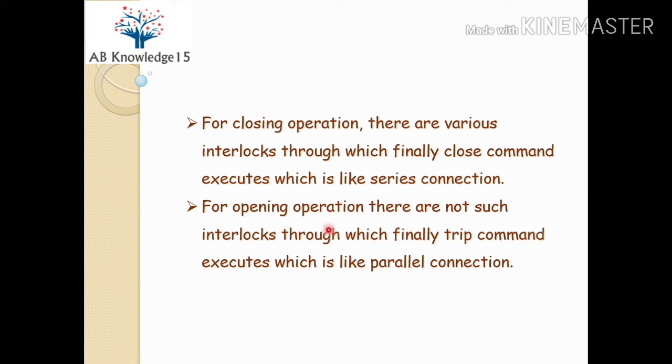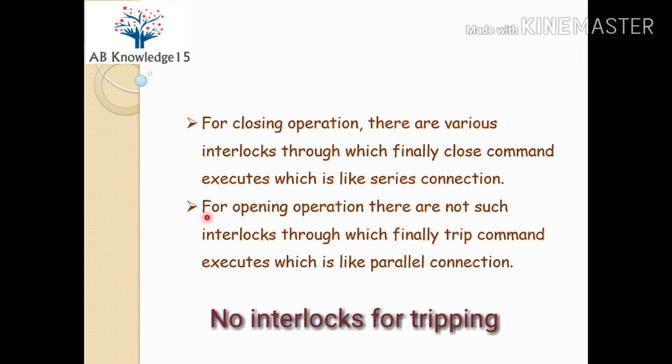And talking about the opening operation, there are not any such interlocks through which finally trip command executes, which is like parallel connection. If you see the tripping circuit of any circuit breaker, then you will see that parallel connections are given for tripping of circuit breaker. If any relay is giving a trip command, then the circuit breaker trips.